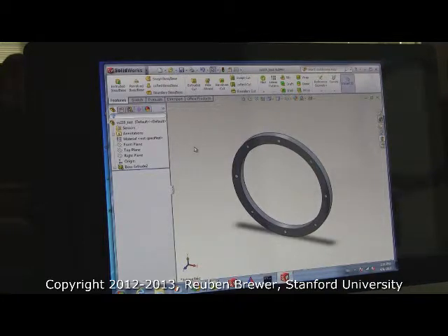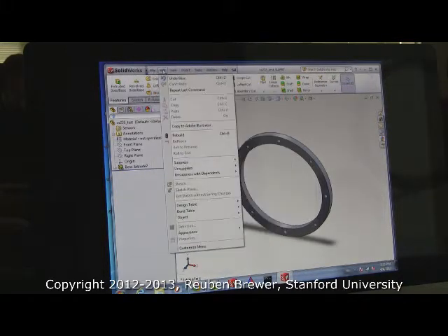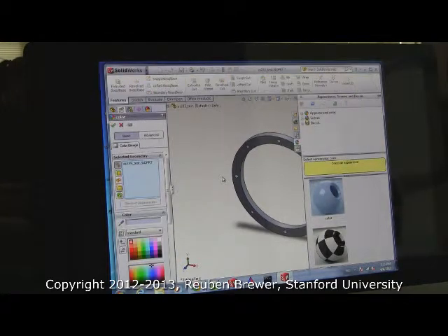Okay, now we're making this out of plywood. Does this look like plywood to anyone? So it's good in your SolidWorks models to make things look at least dissimilar enough from other parts that you can tell what's what. So let's color it. So go up to SolidWorks, Edit, Appearance, Appearance. It should look like this. Okay? Now press this brown down here. See how it changed colors?